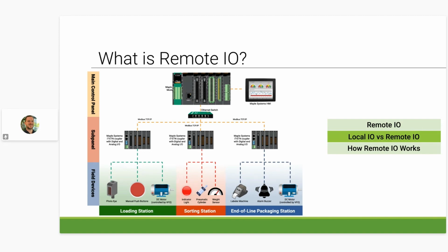With local I/O, as we mentioned, the devices that are connected are generally attached to the PLC, which can sometimes limit the installation flexibility. Latency used to be a bigger factor with local versus remote I/O. However, with modern Ethernet protocols and networking, this is no longer the case. Cost-wise, local I/O can be expensive, especially as the system grows. However, our remote I/O price point offers a more manageable and cost-effective solution for implementing extra devices throughout your facility.